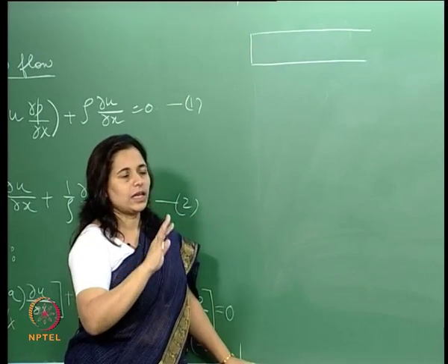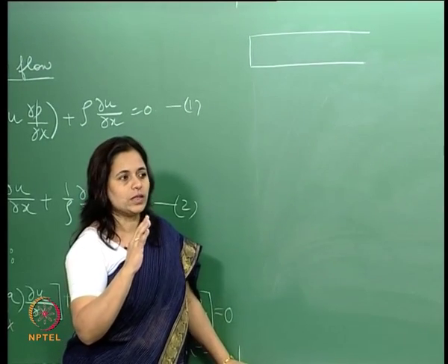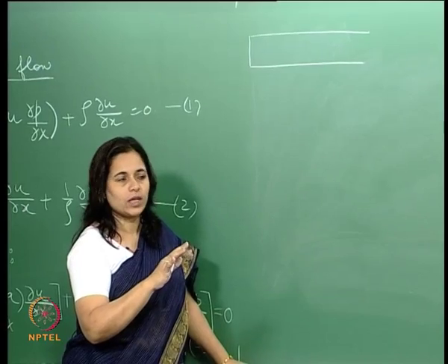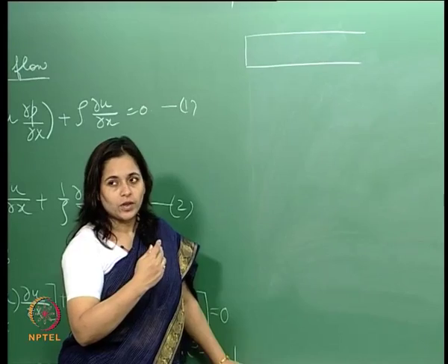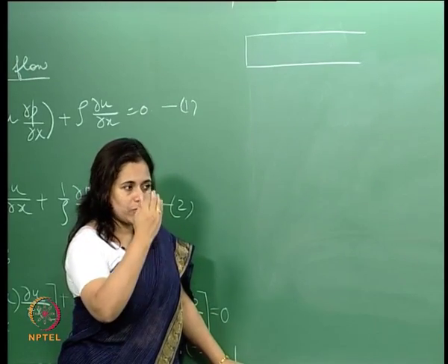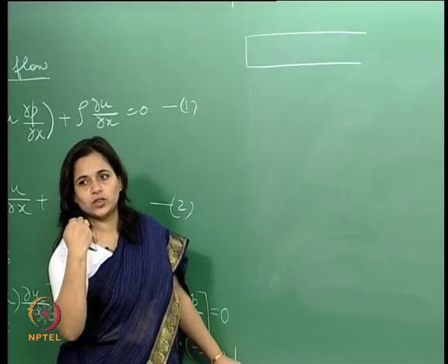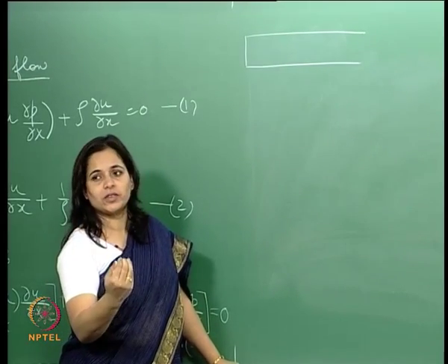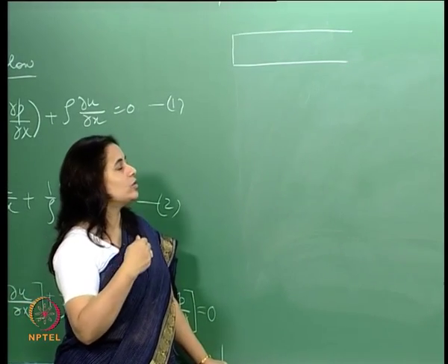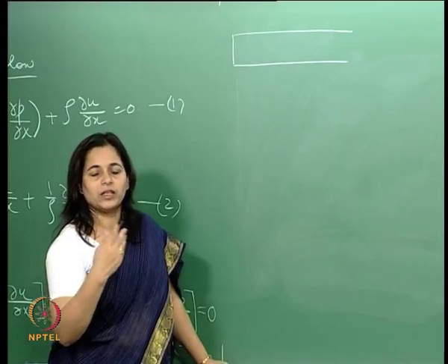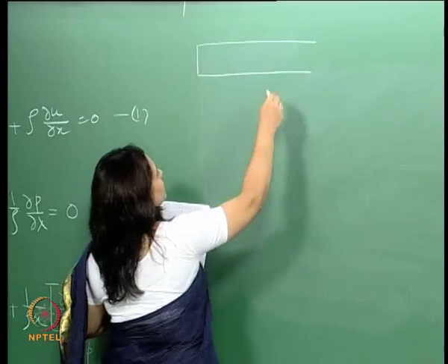We were able to calculate the properties of the fluid behind and in front of the shock wave, and that we have done. What was left to do is, when we break the diaphragm, there is an expansion wave which travels to the left, in the direction opposite to the shock wave, and we are left to find out the properties in front of and behind this expansion wave.